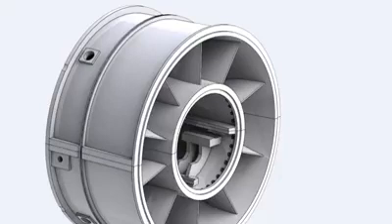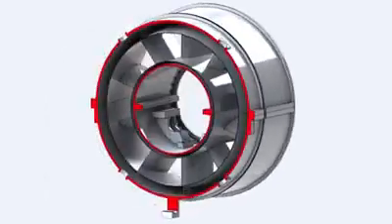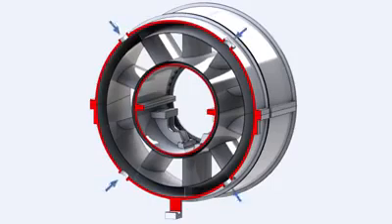This stability is required to keep the exhaust frame inner cylinder, which carries bearing number 3, in the accurate position, avoiding any misalignment. To ensure the temperature stability, air is forced by means of 2 off-base blowers between the exhaust frame outer cylinder and the exhaust frame diffuser surface through 4 ports.